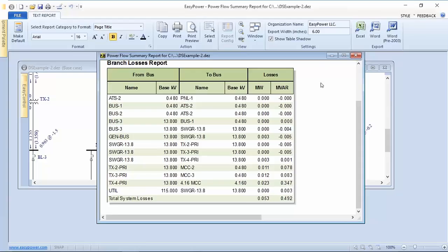database. Okay, next step then would be to save the trend, or save the plots, save the data, and then over time plot the trends to see if any of these losses change. And therein lies the value. So let's kind of go back to my